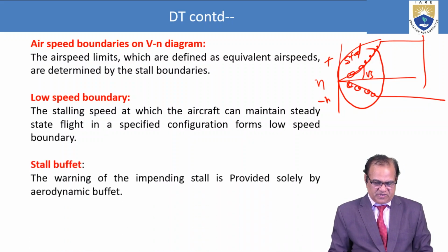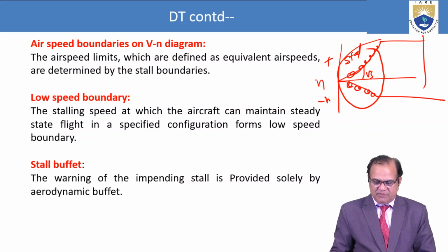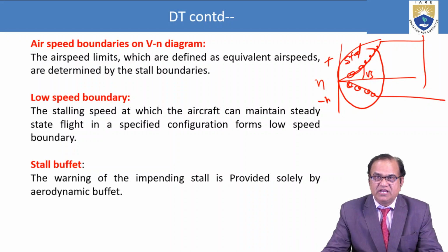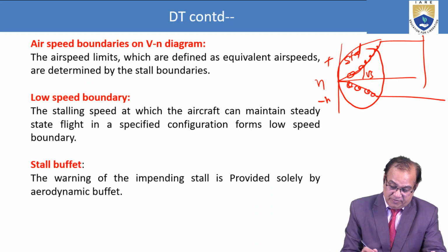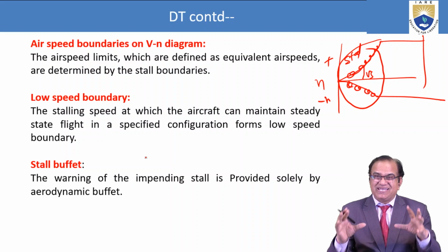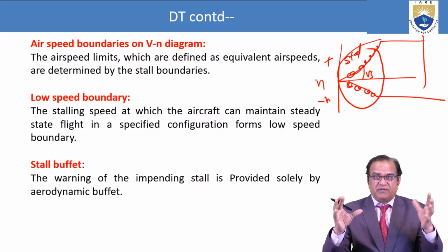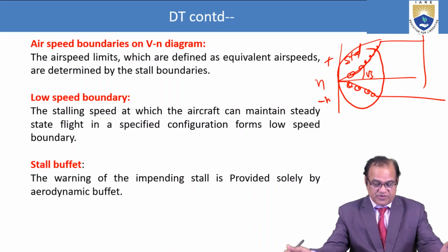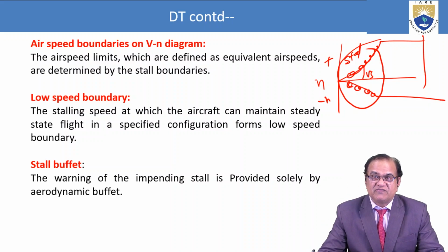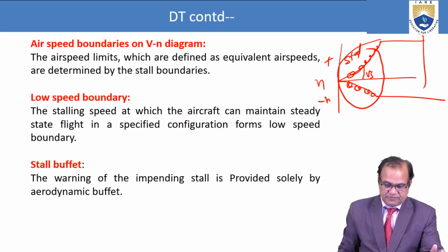Stall buffet. The warning of the impending stall is provided solely by aerodynamic buffet. The pilot will experience some abnormal sound, and the aircraft will start vibrating. So this stall buffet will be observed when the aircraft is about to reach the stall zone.